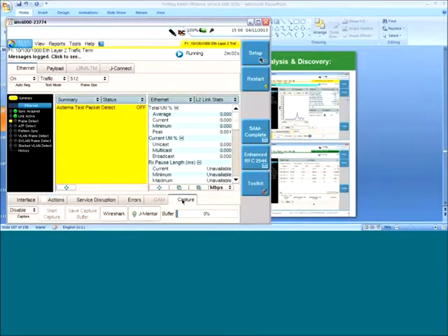If we go to capture here, it allows you to enable. You just enable the capture, okay? Then you say start capture, and then save the capture buffer. And Wireshark is actually built into the equipment, okay? So what that means is that you can create a PCAP file, generate the Wireshark on board the unit, and then simply analyze the data directly on board your 5800, 6,000, or 8,000.